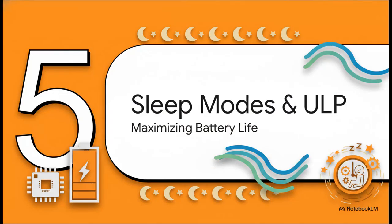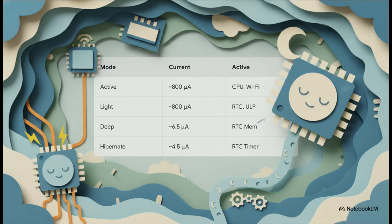Finally, Section 5, Sleep Modes and ULP. Let's talk about endurance, which is absolutely crucial for IoT. This data paints an incredible picture of power efficiency. Dropping the chip into deep sleep reduces current consumption from a somewhat hungry 800 microamps down to a mere 6.5 microamps. And the best part? You still retain your crucial RTC, or real-time clock, memory, so your device doesn't wake up with complete amnesia.